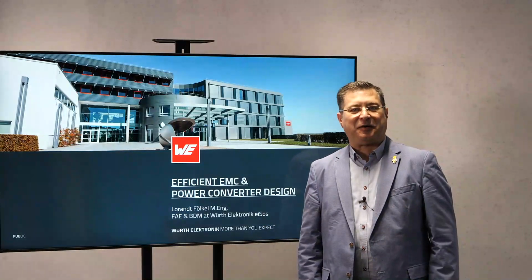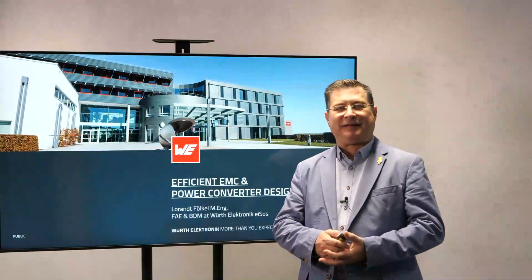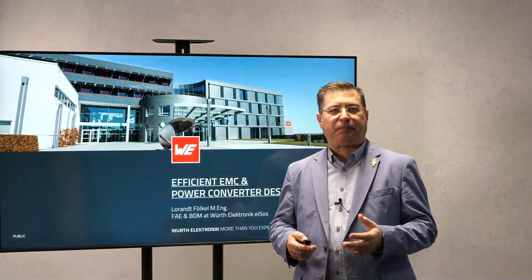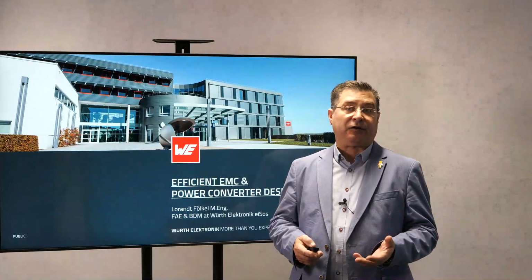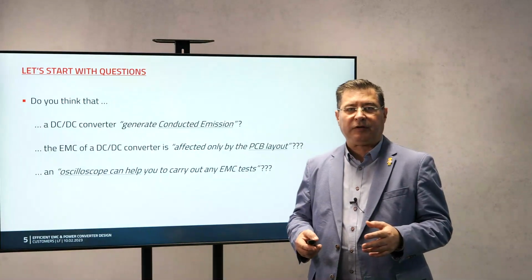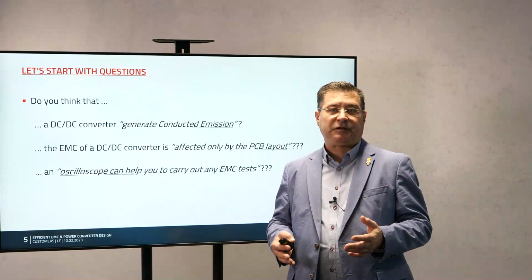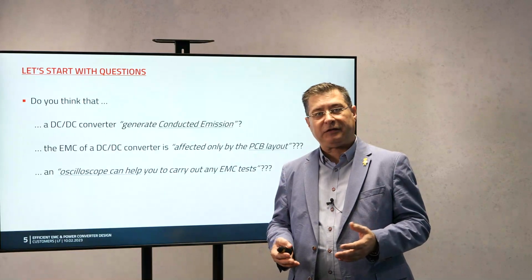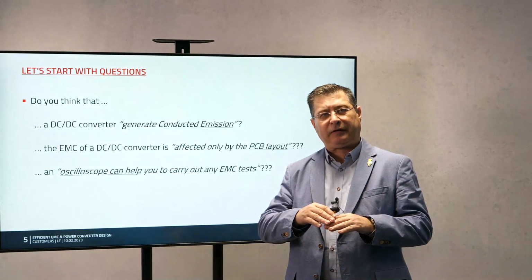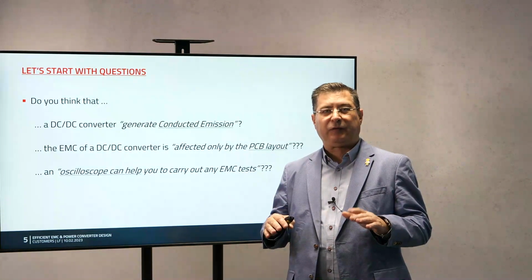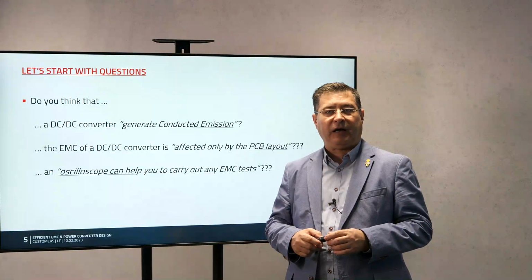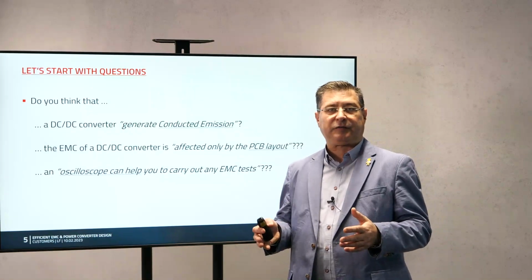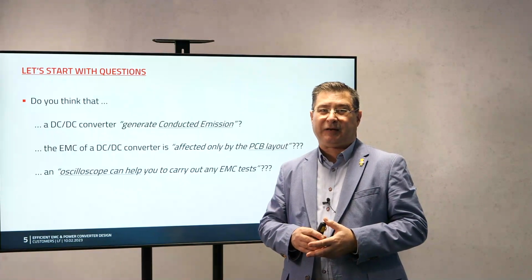Thank you, Markus. I'm very pleased as well. My name is Laurent. I prepared some topics about how to make a power supply EMC efficient and also power efficient. Even if you build a DC-DC converter, you know that it can generate conducted emission noise. Many of you have already had this experience. And if you make a perfect layout and a perfect ground plane, it will not be enough to pass all the EMC tests. If you have a scope with only 300, 350 megahertz bandwidth, and you want to qualify this product up to 1 gigahertz, it will be almost impossible.